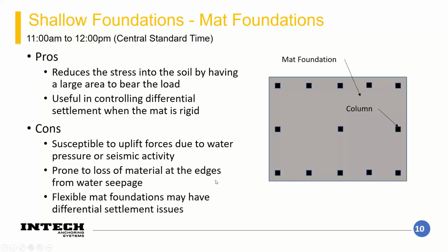Some of the cons with a foundation like this is that you're going to be susceptible to uplift forces from water pressure or seismic activity. You could also be prone to some material loss at the edges of your foundation from water seepage. And the more flexible this mat foundation gets, the more likely you might see some differential settlement.